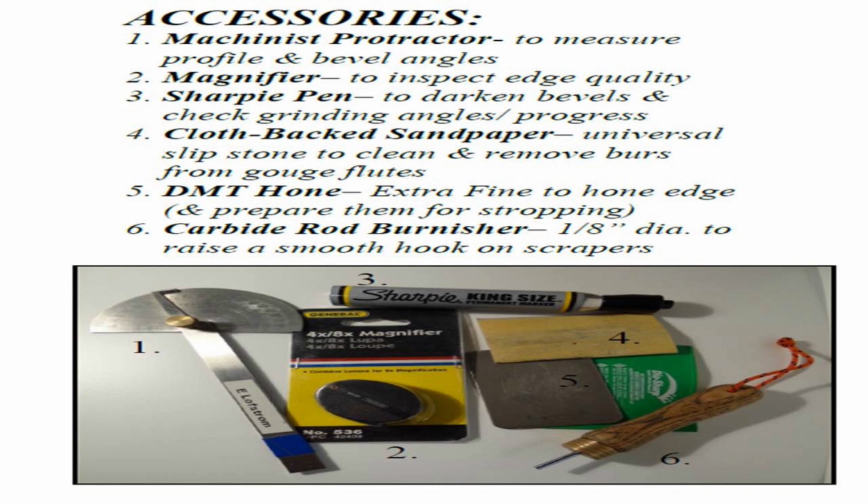And there are two easy types. One of them is, as John had previously shown, a very hard bar that you run over the edge of the tool after sharpening. There's another one John Beasley has in his shop that's actually mounted on the table, with two pins, so that you can hold the tool flat on the jig and use one pin as a lever and then run it across to end up with the burnished hook on the edge of it.